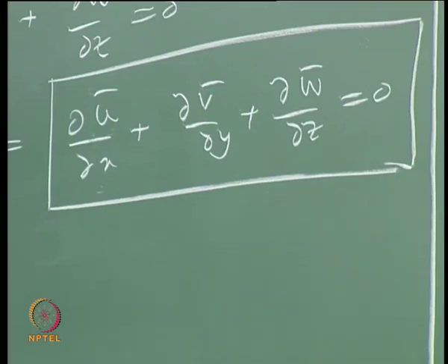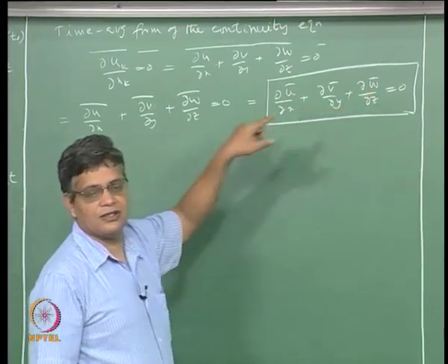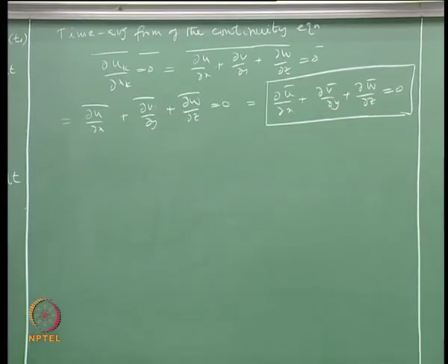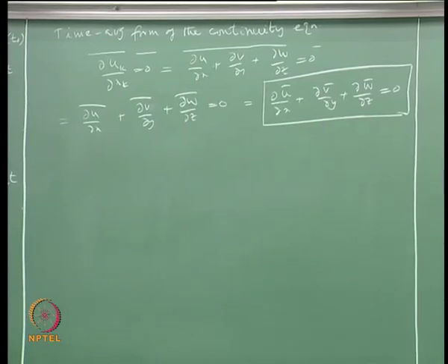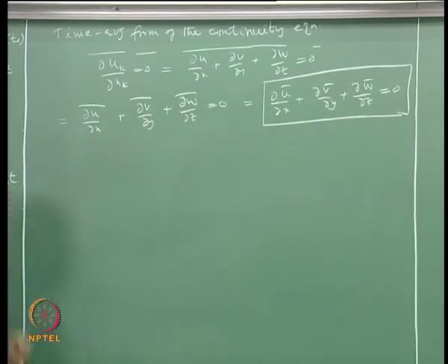If the flow is steady, then ū, v̄, w̄ will not be functions of time, and that is the definition of steady flow in turbulent quantities. And therefore, if the flow is steady in the turbulent flow sense, then we don't have to solve for u prime, and that makes life easier.